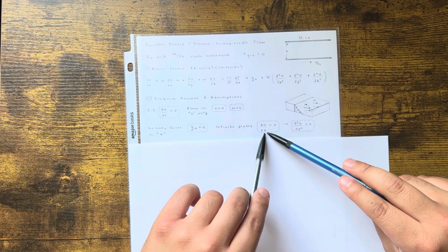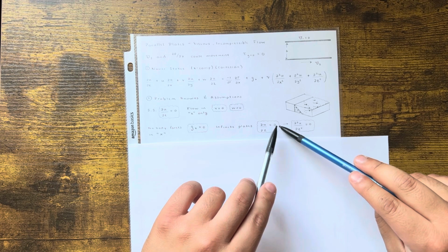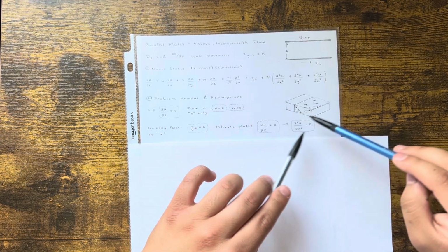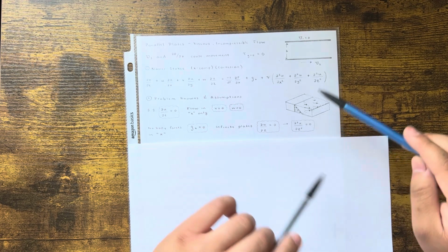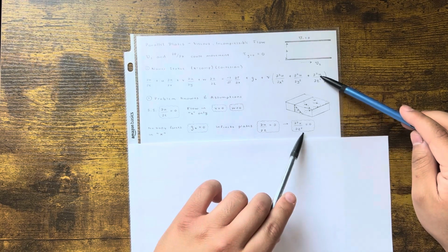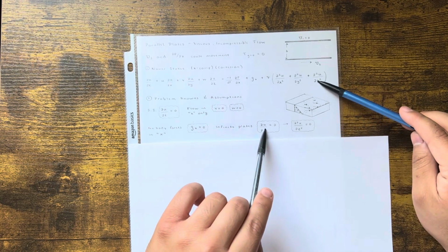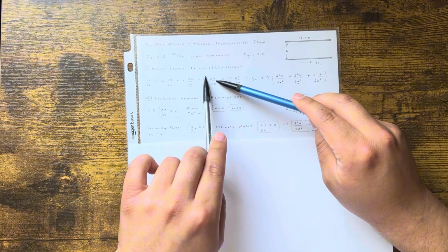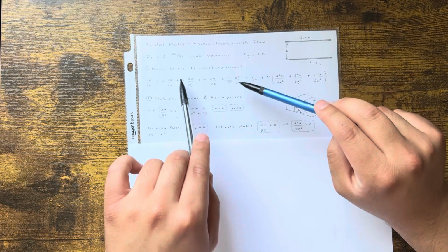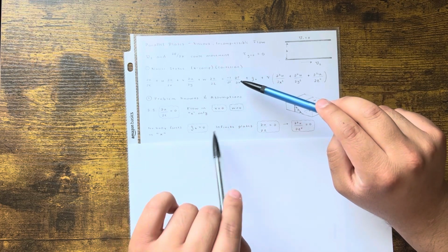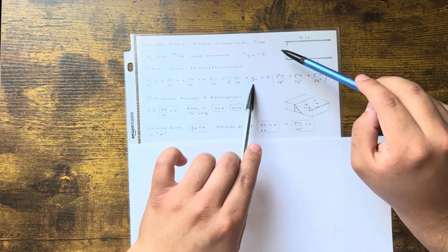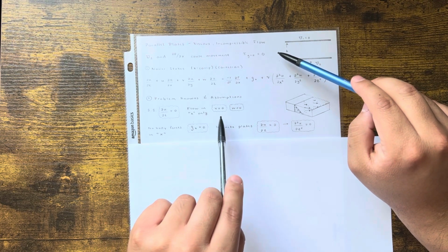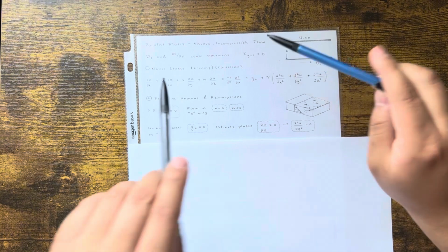Take the partial with respect to Z again, but if you take a derivative of 0 with respect to anything, you're just going to get 0. So these two go away. Now we canceled this term, delta U over delta Z. But this one was already canceled because of W, so we canceled both of them out. Cool. V was canceled because of this. G of X was canceled. What else? I think that's it. Oh, and the steady state, obviously.